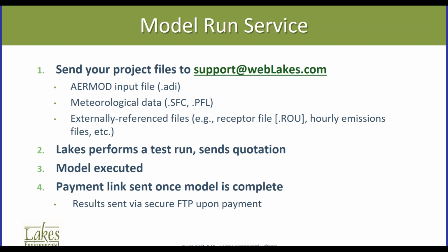If you use AERMOD View, it has a .rou extension. Also if you're using hourly emission files or ozone hourly background data files or just background concentration files. Anything that you might have as an externally referenced file will also need to be included. If you send us the files and we do find something is missing, we'll quickly shoot you an email right back and say, hey, we need this file too so we can get our quote run.